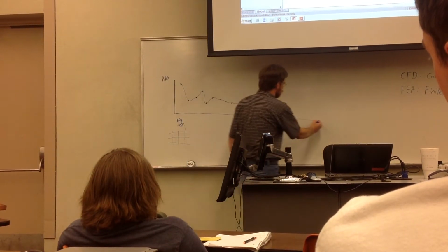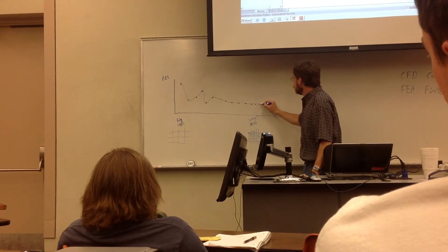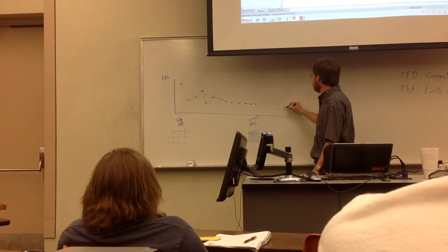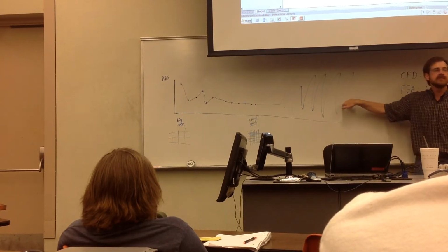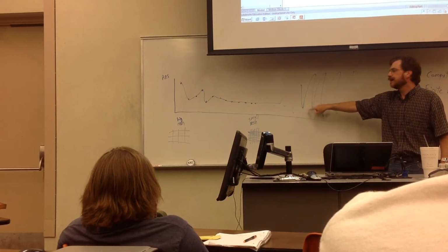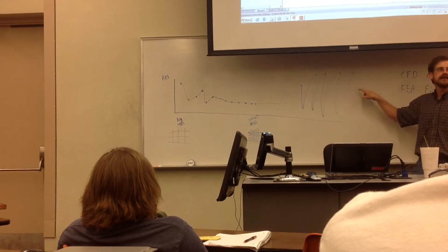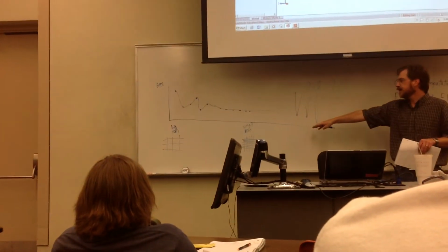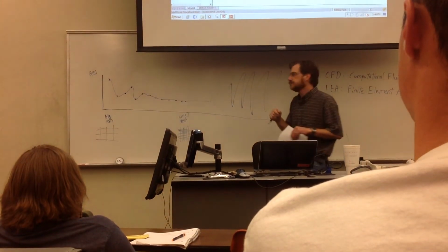smaller and smaller and smaller out here, what would happen is, it would continue to behave well for a while, and then you would start getting all this noise again, and this is simply the round-off error in the computer. Eventually your mesh gets small enough that the round-off errors start piling up, and your results go chaotic, but that has nothing to do with your mesh or with your analysis. It really is just the limitation of the computer.